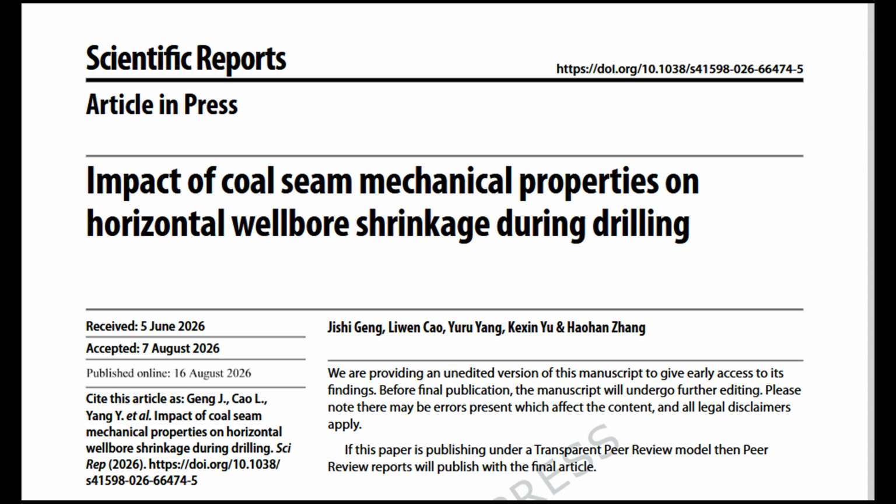Equation 6 is derived by substituting the yield condition into the equilibrium equation. It results in a differential equation that relates the change in radial stress to the radial coordinate. Solving this equation gives the distribution of radial stress inside the plastic zone. Equation 7 is the explicit solution for radial stress at any point within the plastic region.